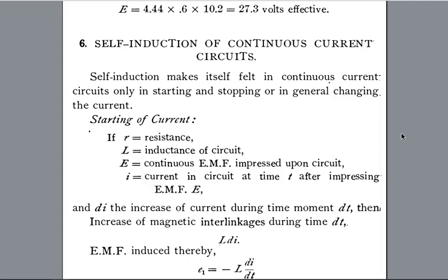Self-induction of continuous current circuits. Self-induction makes itself felt in continuous current circuits only in starting and stopping, or in general changing the current. Starting of current. If R equals resistance, L equals inductance of circuit, E equals continuous electromotive force impressed upon the